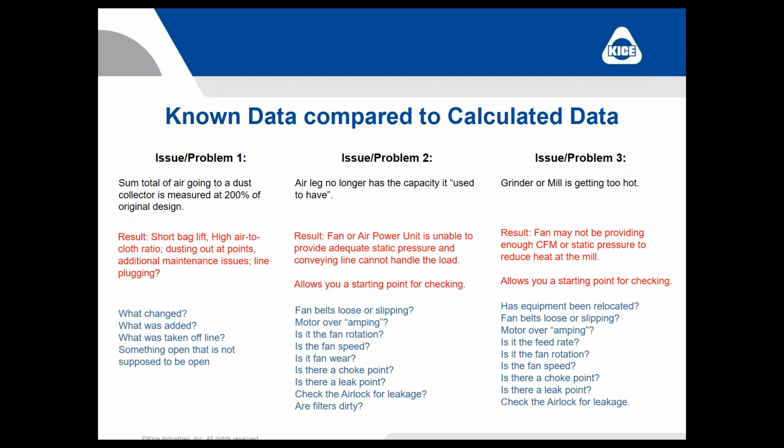What's going on? Well, I can tell you probably got short bag life, you got high air to cloth ratio, you're dusting out in the filter possibly, maybe you got line plugging, lots of different things can be going on. You got to ask yourself what changed, what was added, what was taken offline, something open, full open that's not supposed to be. So you can start to kind of dial in on what the issue might be.